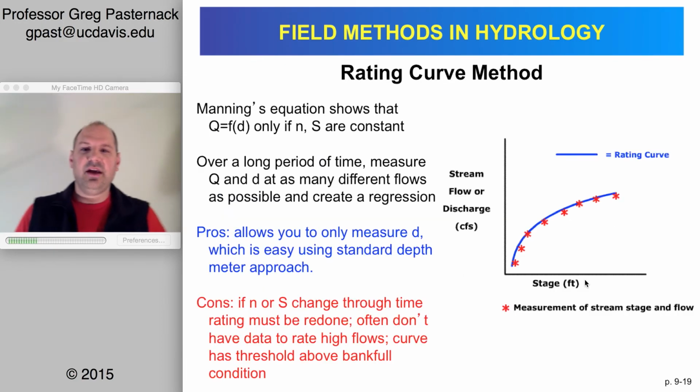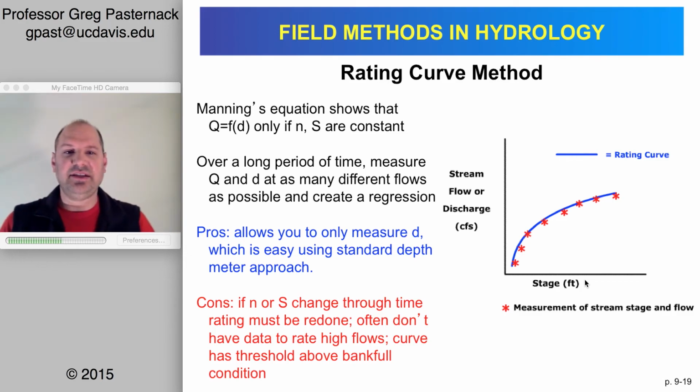The whole point of getting Manning's equation or Chezy's equation is not just to compute one discharge, but to be able to create something called a rating curve. You may be familiar with the term rating curve, in which one would use the velocity area method or an ADCP direct measurement or a flume, and you would make those observations and then fit a best line. And so that's what's shown here is like a best line fit to the data that's a nonlinear fit.